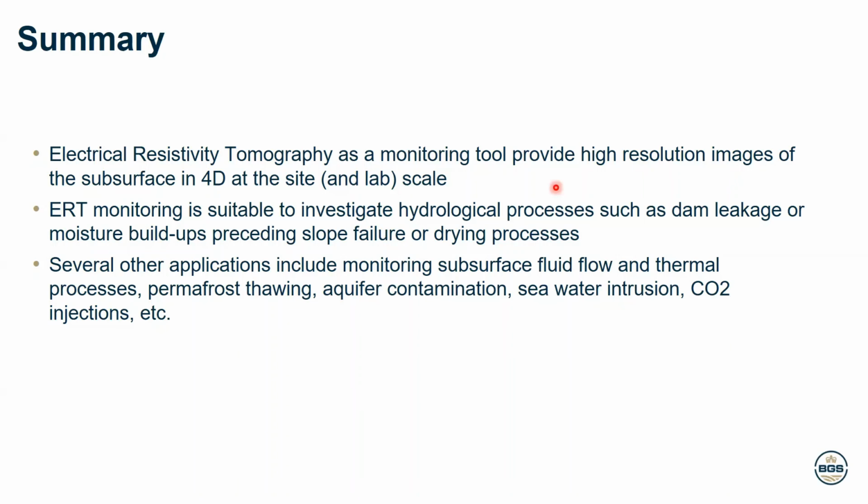ERT monitoring is suitable to investigate hydrological processes. I showed dam leakage or moisture buildups in landslides, but several other applications include monitoring of thermal processes, permafrost thawing, aquifer contamination, or seawater intrusion, and so on.